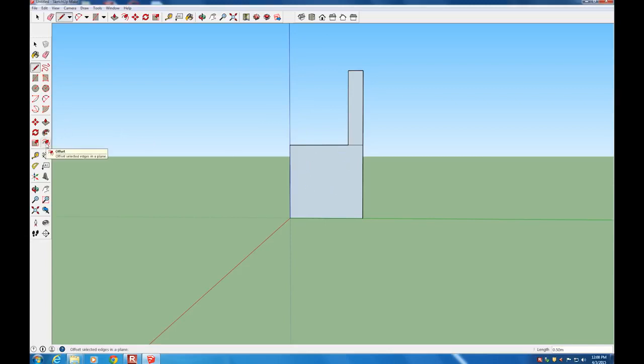So next we're going to add an offset from the outer edge of the chair that we're going to use to create the truss structure. So go over to the Offset tool, the Large Tool Set, and then as you hover over the face, it'll highlight blue, and then click and start dragging inwards, the direction you want to go, and we're going to make this offset 0.1 meters. So I type 0.1 and click Enter, and that's created.